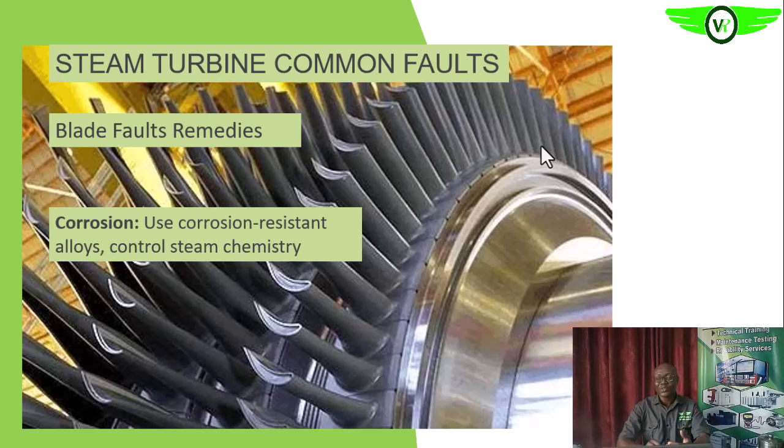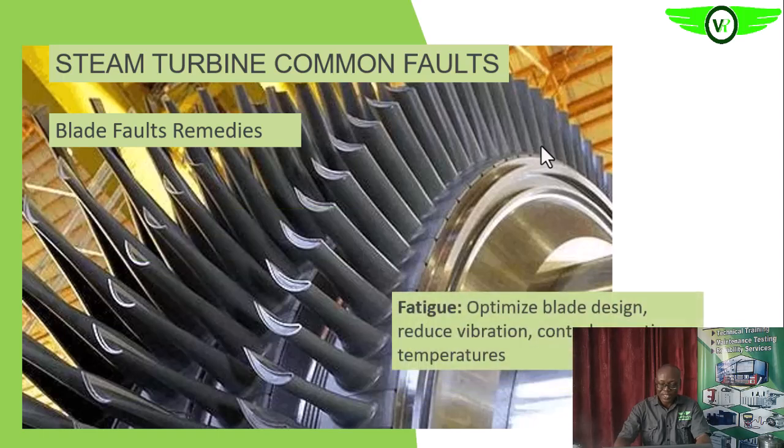So we also need to add chemicals that will assist us so that such precipitates will not form within the boiler. Which means that we need to maintain our blow down system and also the chemicals that prevent scale formation. We need to use all of these in the water treatment before it goes into the boiler.